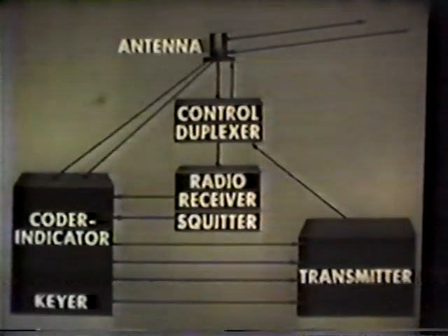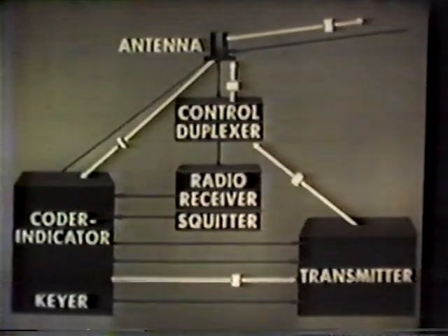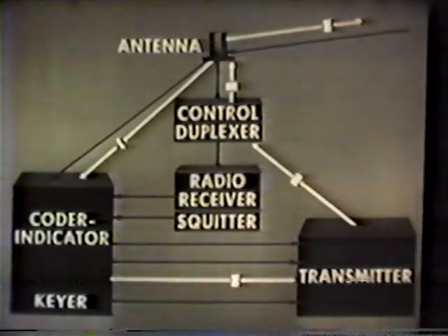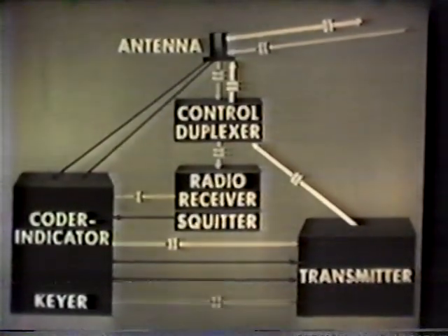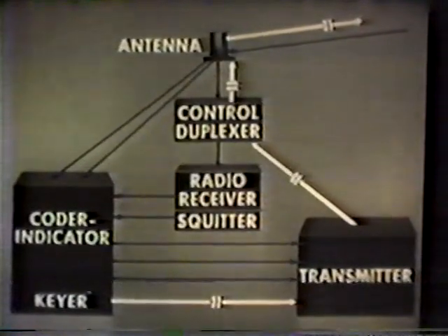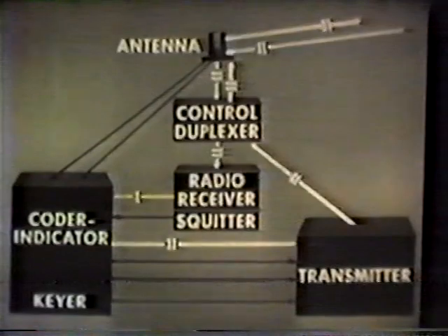We can now see that the URN-3 signal consists of fundamental and auxiliary reference burst pulse pairs, the distance interrogation reply pulse pairs, and the Morse code pulse pairs that momentarily replace the distance response pulses when the identification is transmitted.